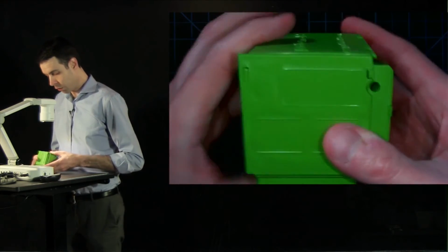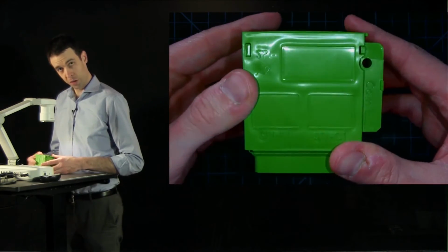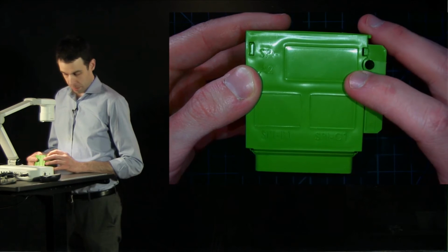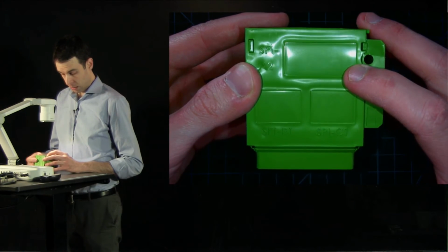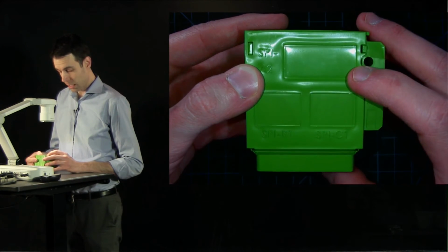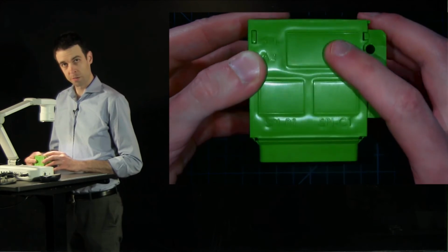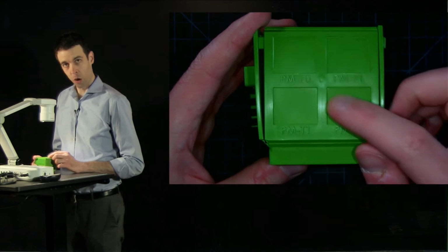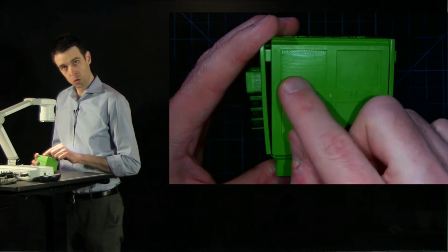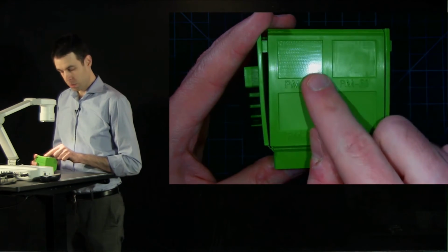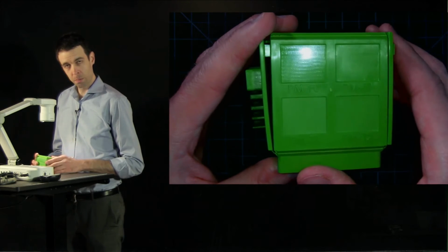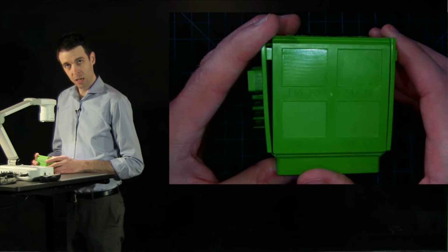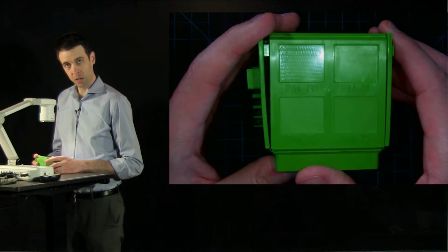And then on some of the other faces we see different surface finishes. And we know that by finishing the mold surface we can affect a finish onto the injection molded part surface. So you have shiny faces all the way down to intentionally roughened faces and faces whose surface matches the machine surface of the tool. And I think through the reflections you can see the evidence of milling machining on this face.